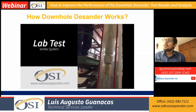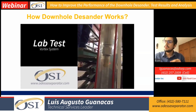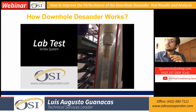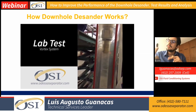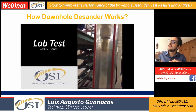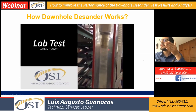So the video is going to show you how the mixture of sand with fluid is coming through the intake. In this case, we're using a screen as an intake. So the fluid is going through the screen and then is flowing through the veins of the helix. And if you see, all the mixture is going to flow radially. The radial forces are causing the heavier phase, which are the solids, to be concentrated at the bottom.